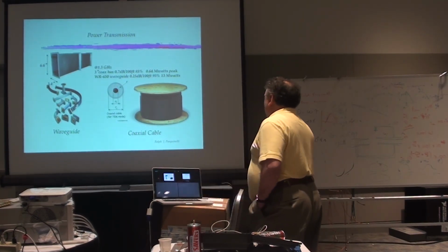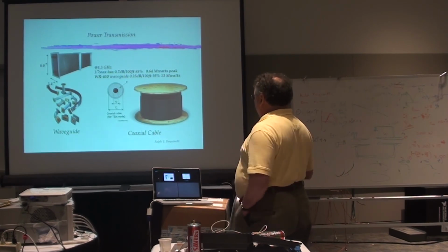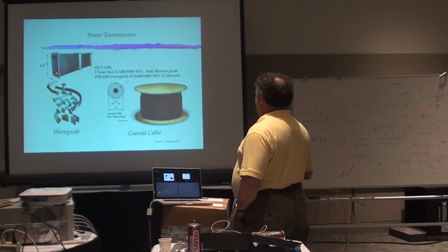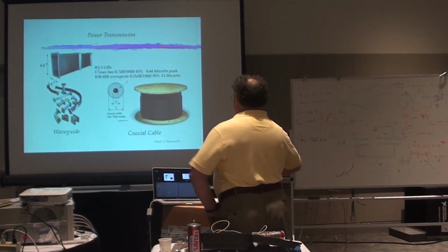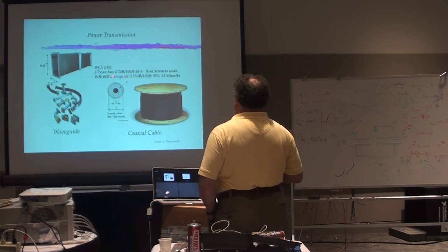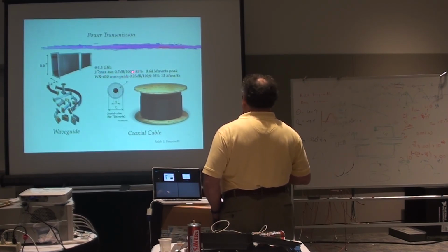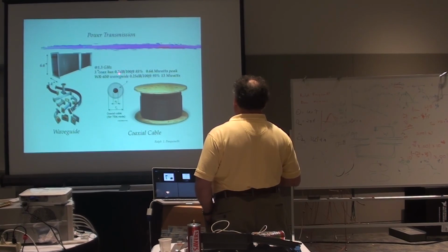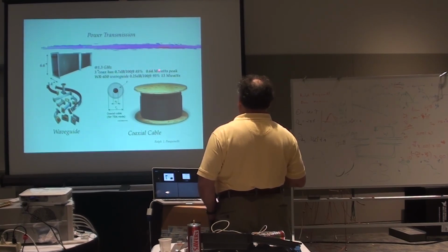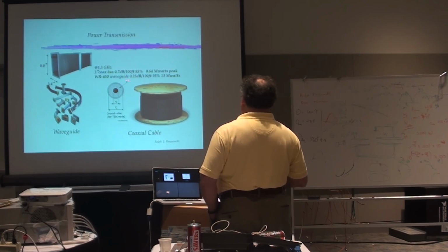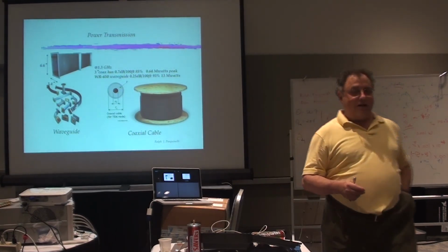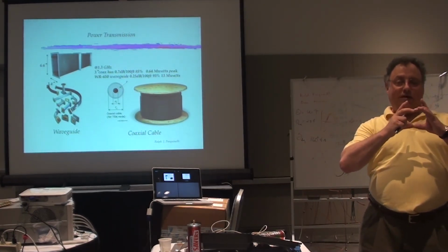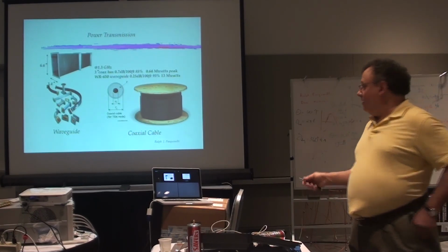Well, here, if we're doing 1.3 gigahertz, which is a popular number, here's the waveguide for that, which is WR650, and it's like 6.5 inches by 3.5 inches. And that's a pretty good chunk of cross-section that you have to make room for in your gallery. Now, you can also use a 3-inch coax at that point, and it has an insertion loss of about 0.7 dB per 100 feet, and it can only do 640 kilowatts, but the waveguide has a quarter of a dB per 100 feet and could do 13 megawatts. Okay, so now you've got a decision to make. That 3-inch coax occupies half the volume of the waveguide, but I have to pay for those lost watts.